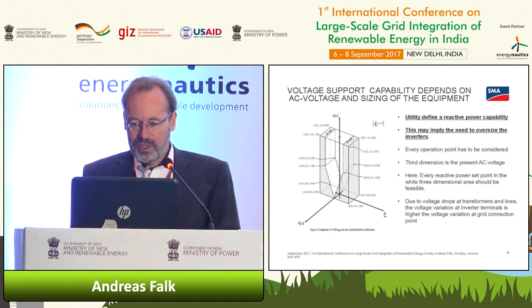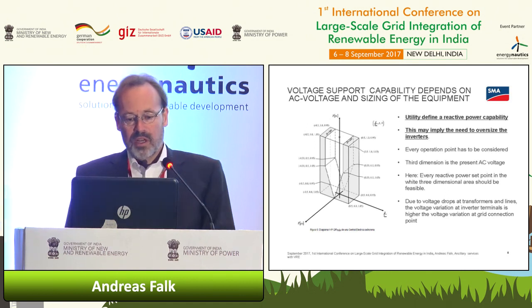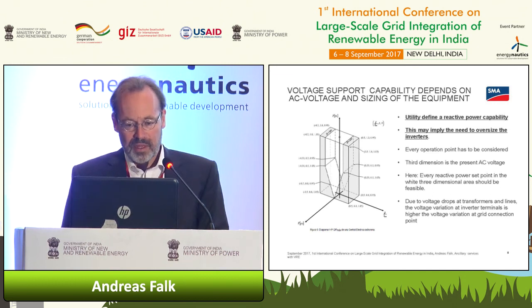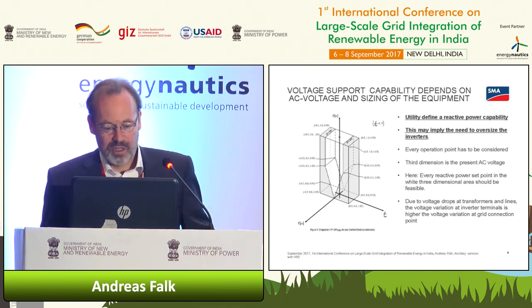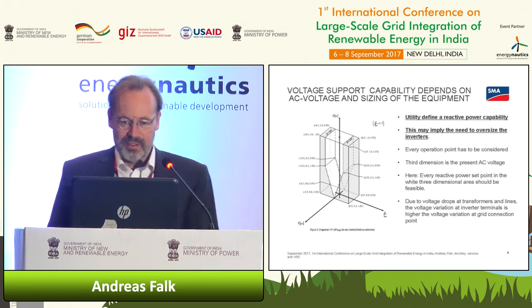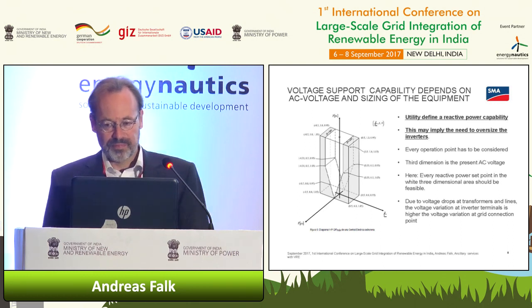And every operation point has to be considered, because we have not a two-dimensional problem but a three-dimensional problem. The reactive power capability depends on the one hand on the active power, on the other hand on the present voltage.